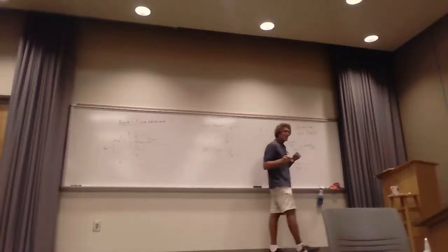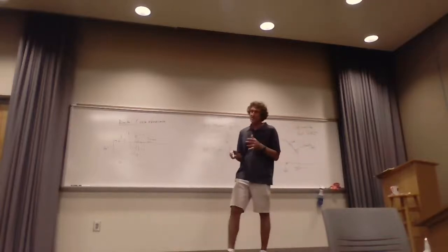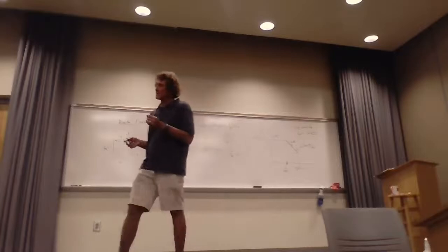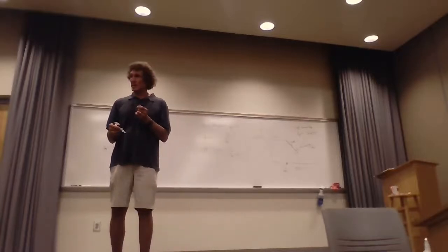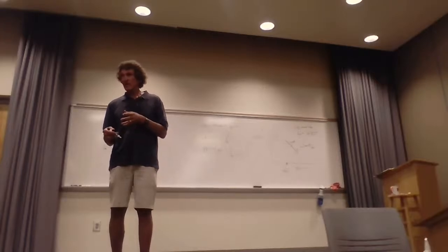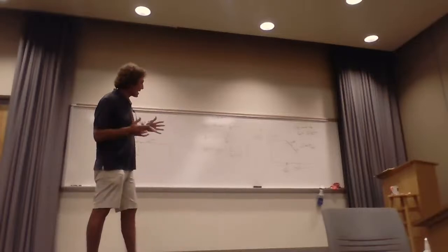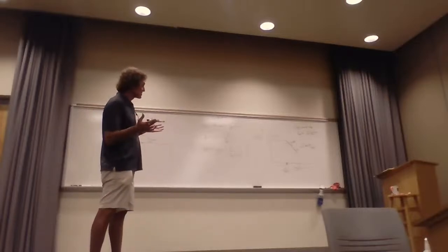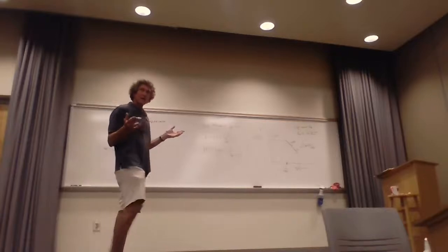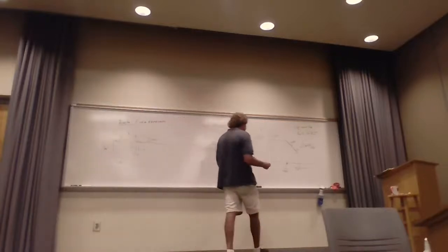Now, remember when you had Bode plots? If you had a single pole, they went down or up at 20 dB per decade, right? If you had an s squared or a double pole, it's 40, an s cubed, it's 60. Do y'all remember that back in the days when you had circuits, or I should say signals and systems? It's the same here. Now, I got a question for you. How do you find this minimum here?